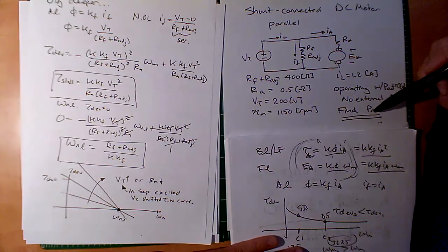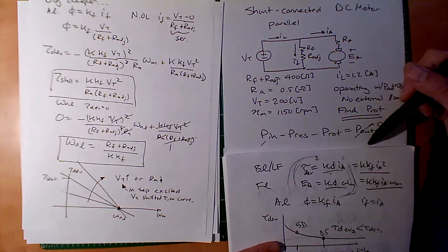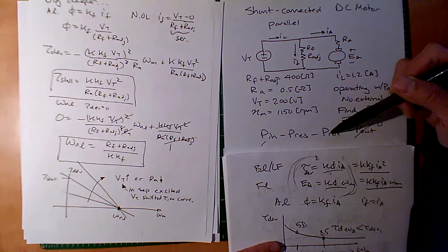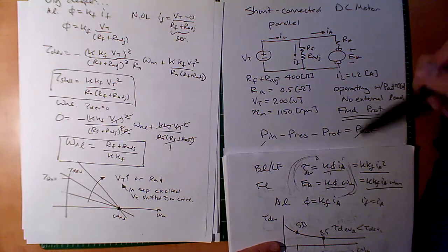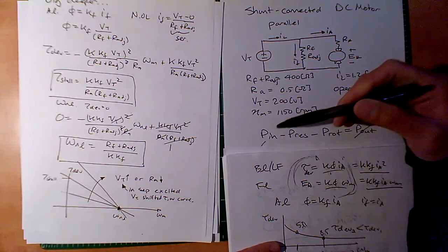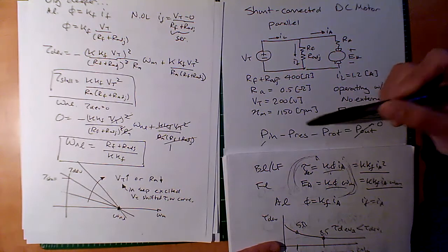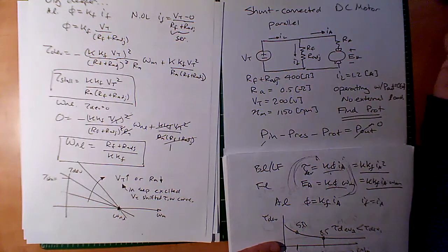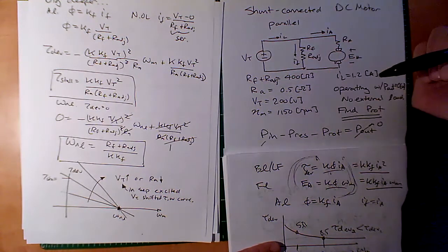Well, one equation where the energy of the rotational losses showed up is the energy balance. So the input power minus the resistive electrical losses minus the rotational power equals the output power. And the problem is claiming that this is 0. So if we can calculate these two things, we can solve for this one. All right, let's look at the input power. We can just take IL times VT, is that right? Good, we have IL, we have VT, so that's a known quantity.